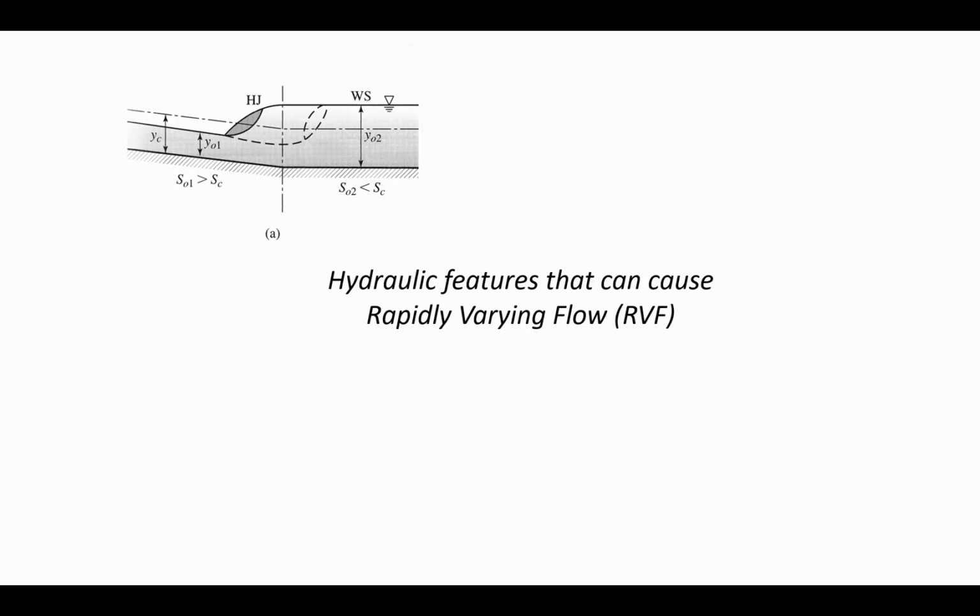And if you've ever gone whitewater rafting, maybe you've seen a hydraulic jump. I've done it a couple of times on both the New River and also the Gauley. You can see these usually behind a steep drop, where there's a standing wave. Hydraulic jumps can occur when you have a steep section that then goes to a flat section. I think that's what's happening, at least in the locations I've seen on the New River: there's a big drop down and then the standing wave forms after that. Here it's showing it can be before or after, depending on the relative magnitude of the slopes. So this is one thing that can cause a hydraulic jump.